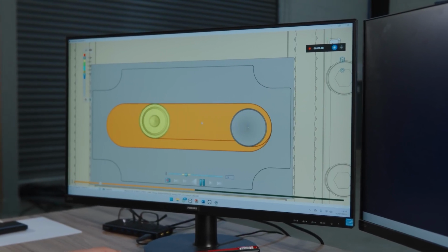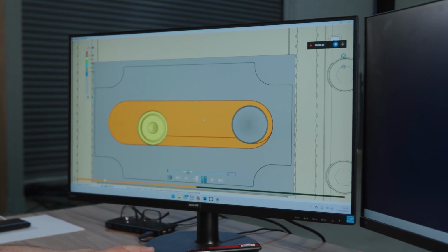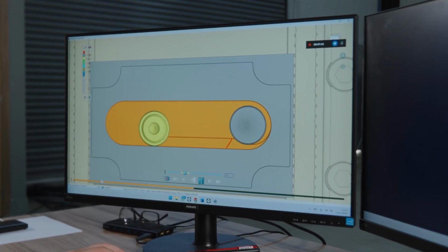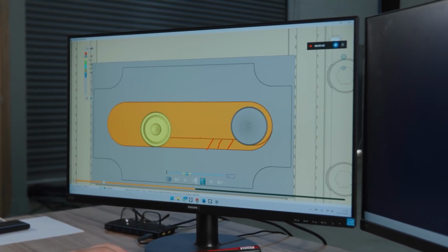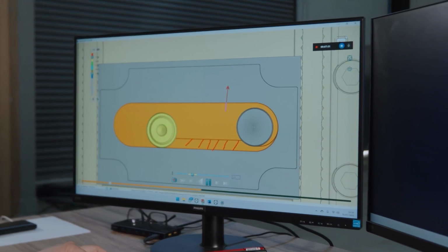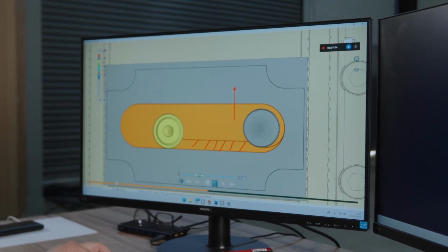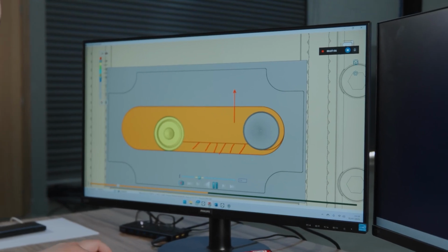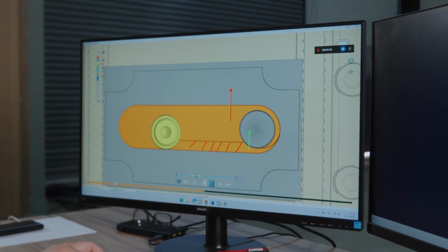However, when it comes back to continue the cut and make the overall width of the keyway, here less than 20% of the tool is in contact with the part. In other words, at this point I could use less feed, and at this point here I could use more feed. On this part I have 6 processes where I should have variable feeds for each one of them. That is, more feed, more productivity, and the part spends less time on the machine.